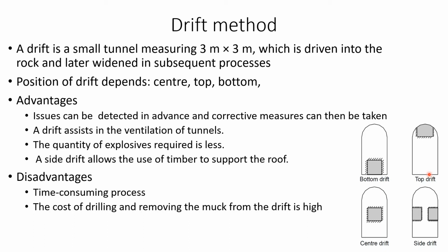The position of the drift again depends upon the local condition. As I told you, it can be provided at the center, top, bottom, or at the sides. Field experiments have shown that the central drift is the best choice, as it offers better ventilation and requires lower quantities of explosives. Once the center drift is driven, then expanding it requires less explosive.